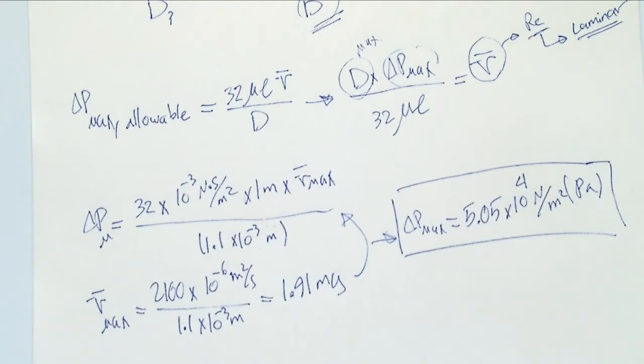So you need to know the uncertainty in the manufacturing process and apply that in your design, because you have to make sure of the dimension of the pipe, so that plus or minus this uncertainty in manufacturing, the whole pipe system that you are designing stays below, and not close to, turbulent flow.